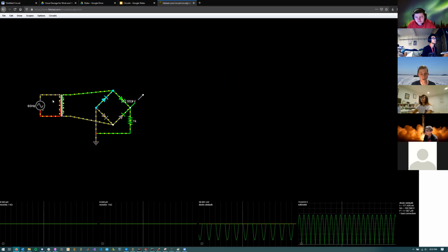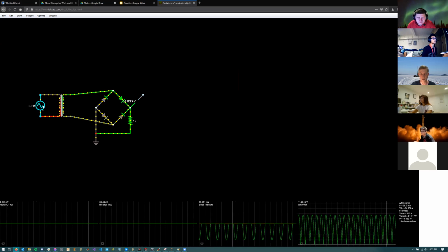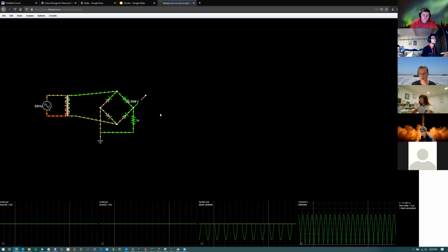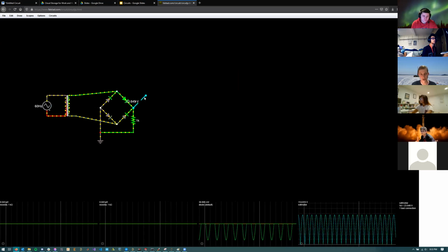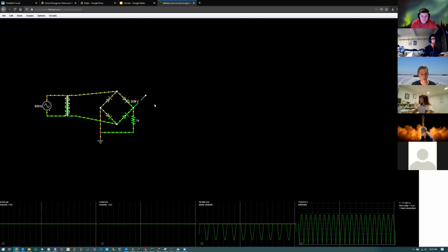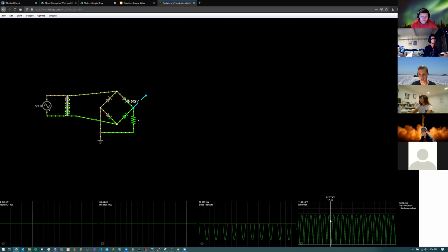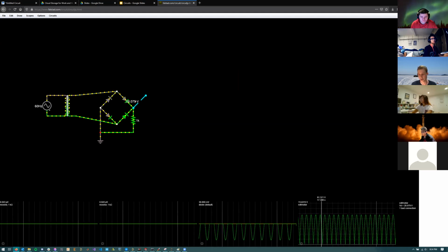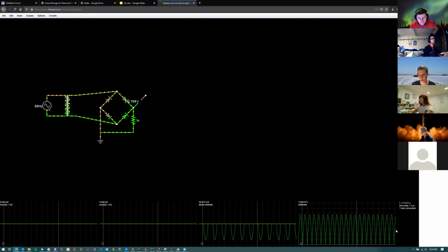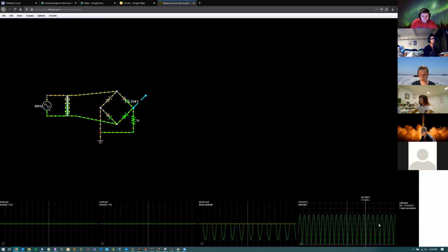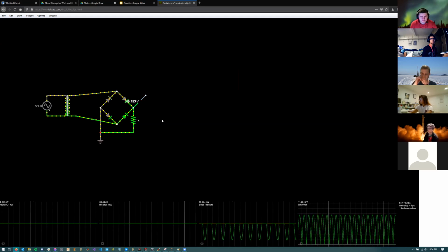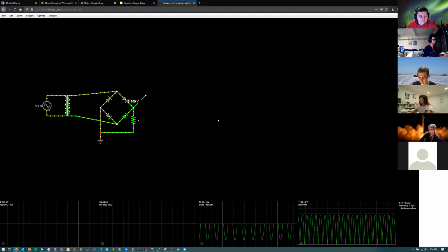We don't use AC voltage; however, we use switching regulators. I won't get into those, but the way a switching regulator works is it switches the voltage on and off, essentially pulse width modulation. So we need to smooth out this spiky plot of voltage here.